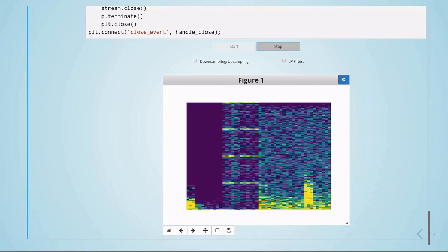Here we just have one low pass, but if we have a downsampling and upsampling rate N equal to 8, we can use 8 different filters, and then we fish out from the aliasing components the frequencies we want, and we end up with the whole frequency range, and we can reconstruct the original signal if we have more filters. In this case, we just have a low pass filter, so we are removing some aliasing components, and we just have the reconstruction of 1/10 of the original signal.